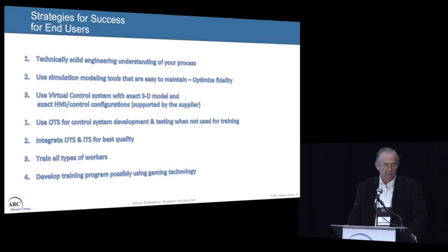Virtual systems and 3D models, with exact control systems, exact control configuration. It's much less desirable to port the control strategy over to the simulation. This PID is not going to be the same as that PID. Use OTS for control system development and testing, because if you don't, that means you're doing development and testing on the running process. This is not a good idea, but it is done everywhere, or often. You want to test and evaluate how your control strategy is going to work in a safe environment instead of testing it live. Oh, I accidentally closed the wrong valve, and it's easy to do.